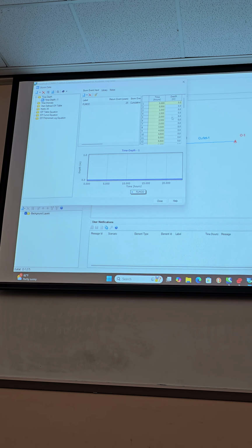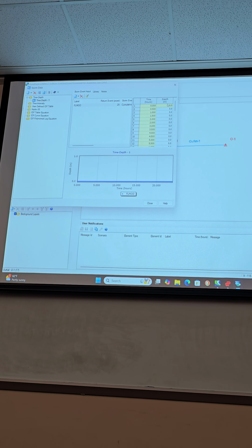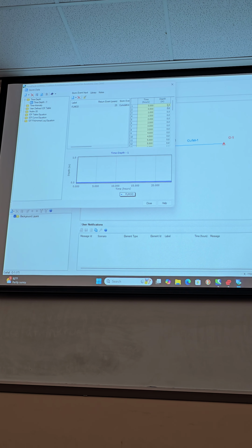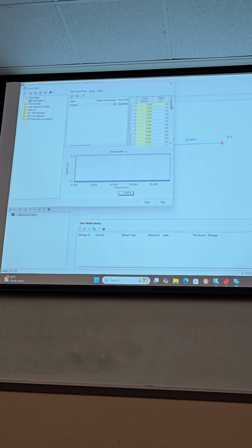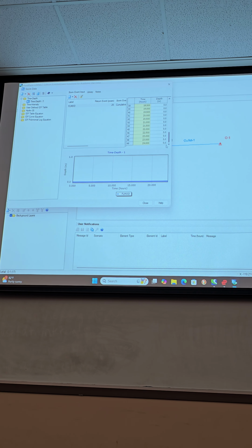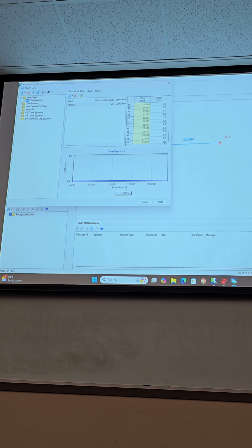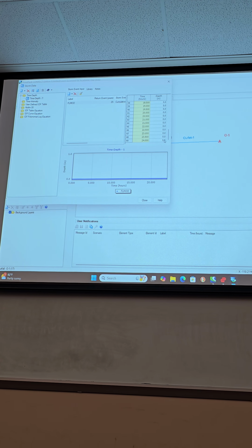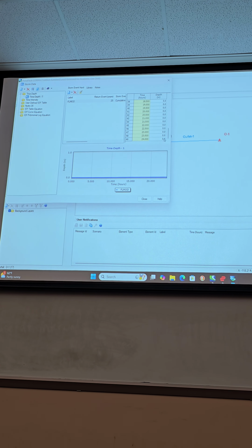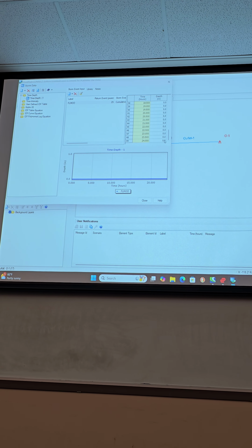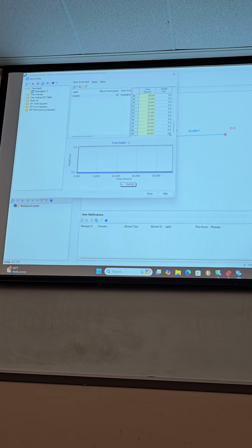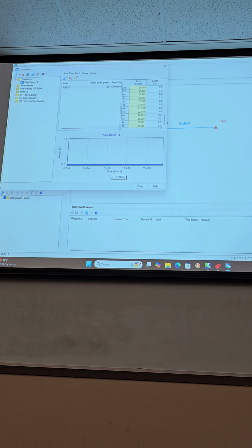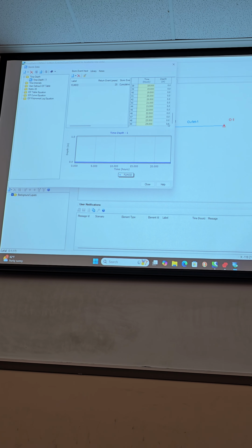So now I have this table. And so this table will be based on the ratios that I showed you before we started. And you're gonna put in the incremental depths of rainfall from 0 all the way up to your total depth at 24 hours, which in the example I showed you was 8 inches. So you're gonna start off at 0, and then using those ratios, it's gonna be like 0, 0.1, 0.2, build up, and by the time you get to hour 24, it will be, in this case, 8 inches. Does that make sense? Anybody have questions on that?